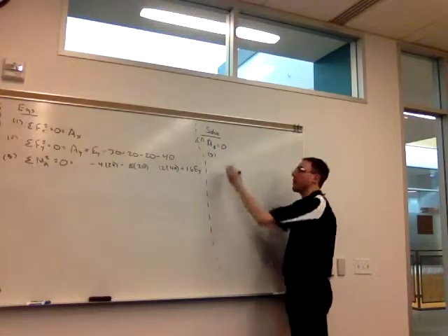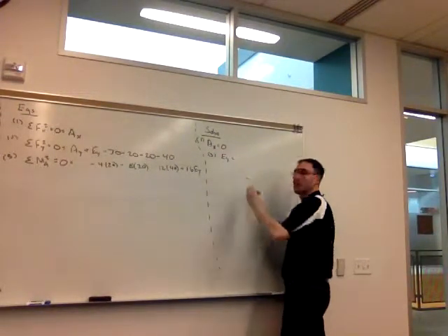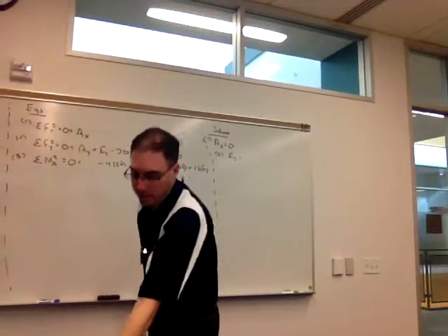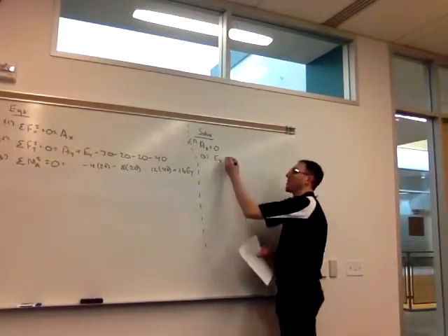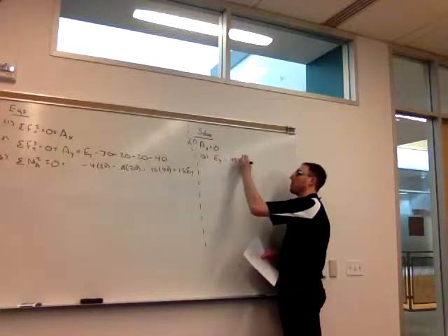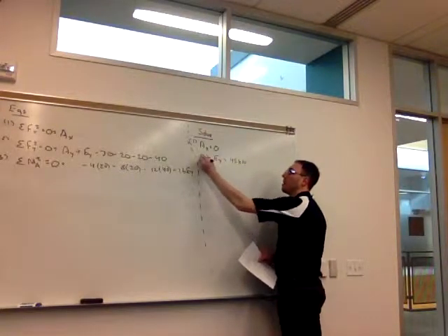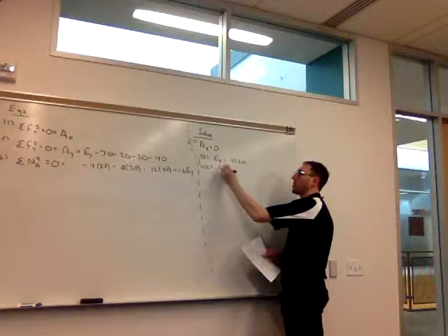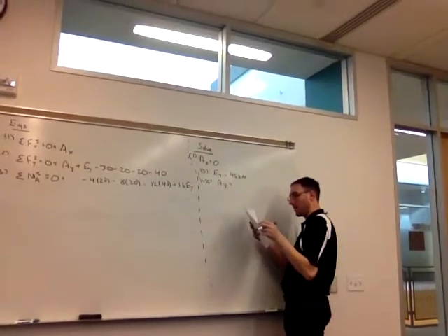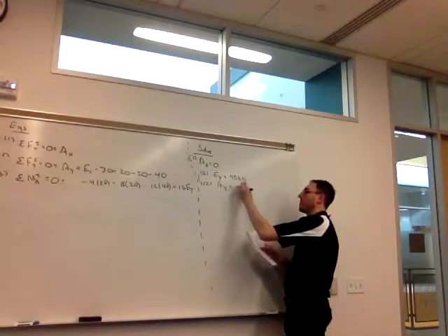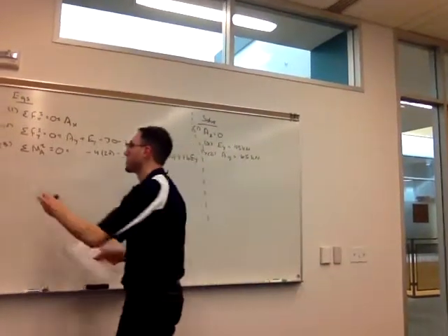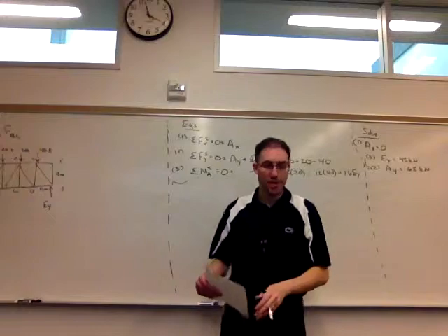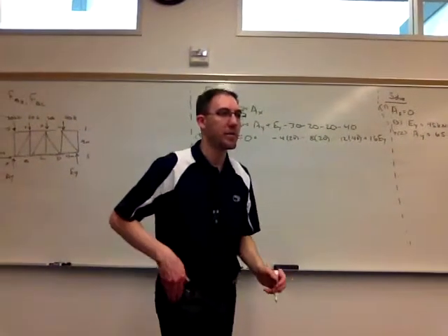So by design, EY is the only unknown in equation 3. So that normal reaction is going to be 45 kilonewtons. Putting that into equation 2, I can get the support at A is 65. All right, so nothing new in this one, just chapter 5, find those supports.